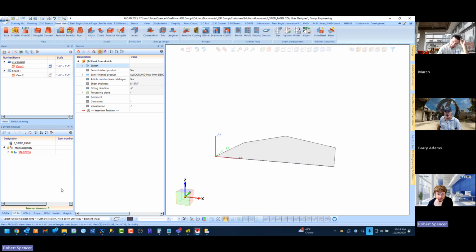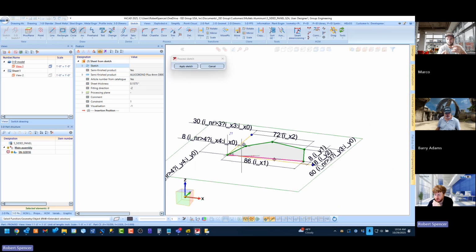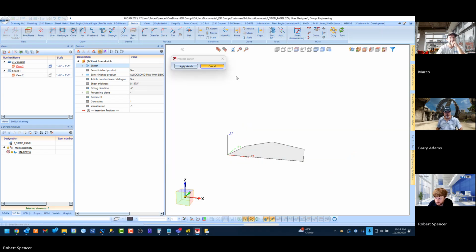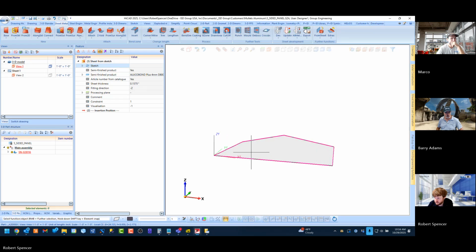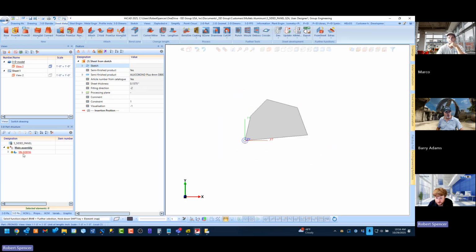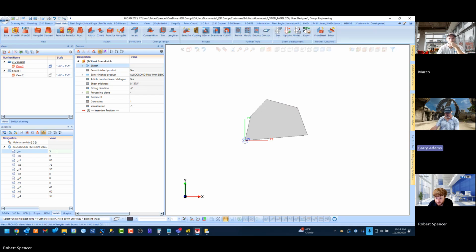Say again. Green? Green means fully constrained. Correct, which is what you want in this case, because we don't want to leave any degrees of freedom unconstrained, because that would lead to interesting results when we go to apply the element on elevation. Now you can play around with it a little bit if you want to. I'll save it. Yeah, that's a good idea.